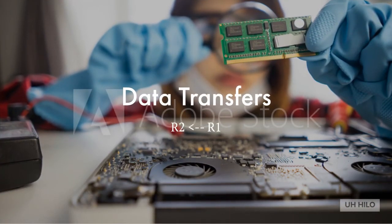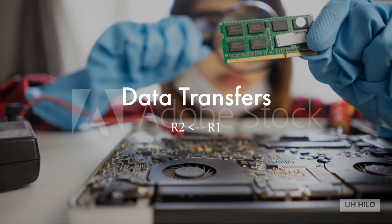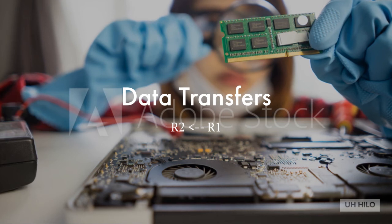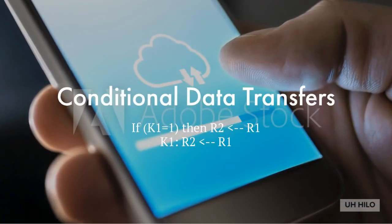Data transfer from one register to another is designated in symbolic form by means of the replacement operator, or the arrow. The statement you see here denotes the transfer of the contents of register R1 into register R2. Specifically, the statement designates the copying of the contents of R1 into R2. The register R1 is referred to as the source, and R2 is referred to as the destination. By definition, the contents of the source register do not change as a result of the transfer, only the contents of the destination.